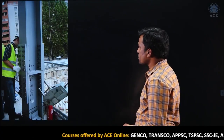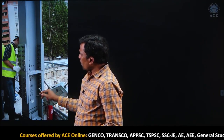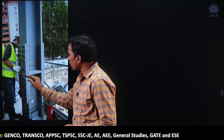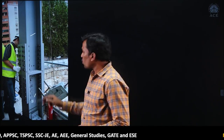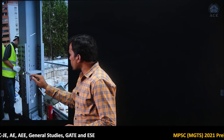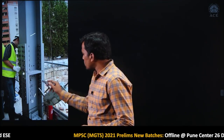Now, if you see this diagram, students, to increase the height of the column, we will use plates. Now, this is the one column, the top column, and this is the bottom column. To connect these 2 columns we need some plates. Now, this is the plate and this is the plate, and this plate is nothing but the splice plate. Now, this is the joint.